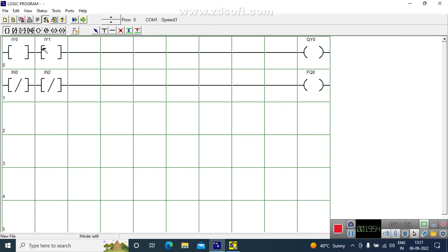Okay, suppose you have say 20 inputs which are in series. So you make contacts here, input 0, 1, 2, 3, 4, 5, 6, 7, 8. Make a flag and put the flag again here on this one as feedback, and you can continue and keep on continuing. So this is the way you can make a big ladder logic. Okay, now we deal with that later on.